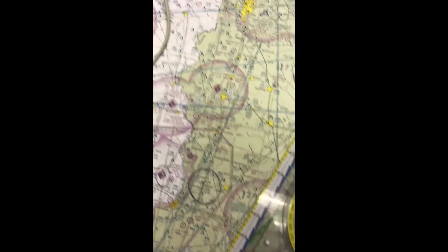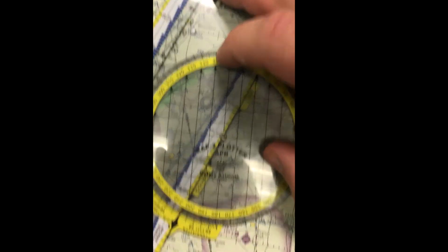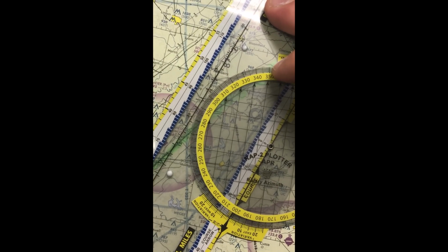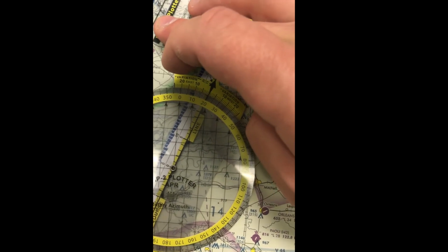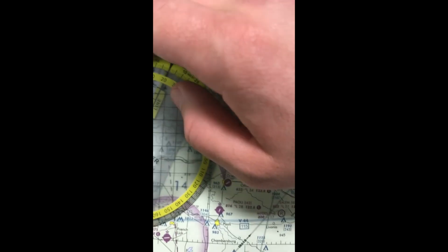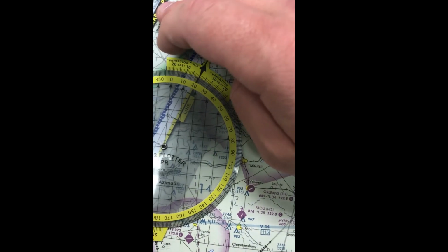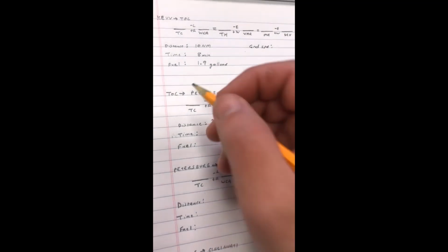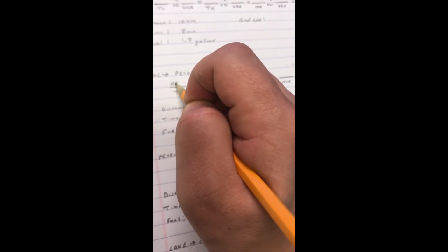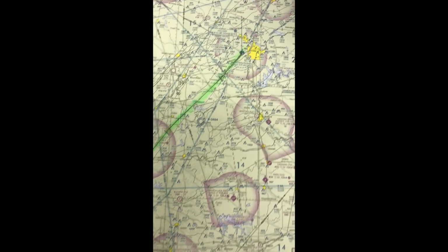We'll say that one is 20 nautical miles. Now we'll get the course for it using our little course arrow here. Spin our bezel until we're lined up along a line of latitude or longitude, and then we can read under there our true course for that particular leg. We're looking at approximately a true course of 020. Now we'll bring that over and plug in that first true course, 020 for top of climb to Petersburg, and then we'll continue that process for the rest of the checkpoints along the route.